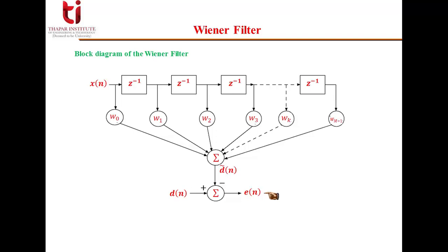Now if we say that our designed filter is an optimum filter, that means this error should be minimum. For that, this en, which is nothing but the difference between the desired and the estimated signal, is the optimality condition we want to achieve. Basically, we are not taking this estimation error as such. We are taking the mean square error of this.